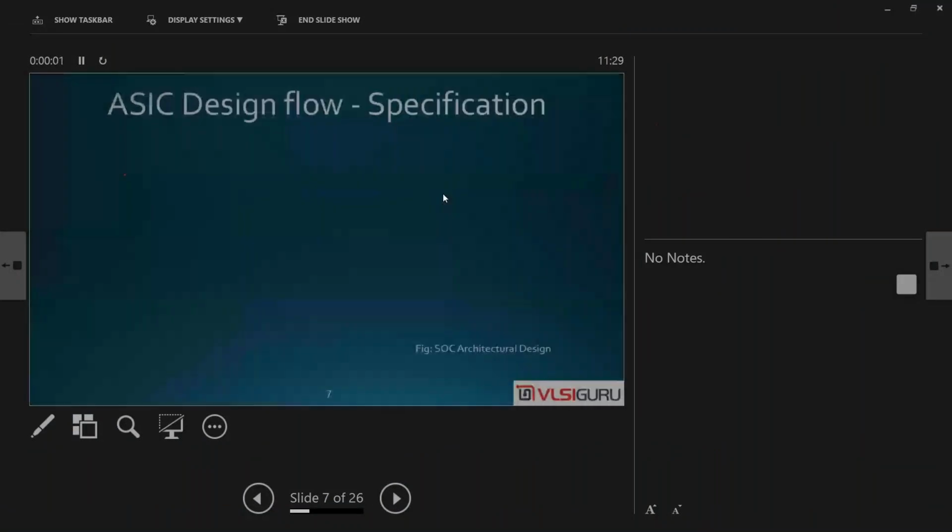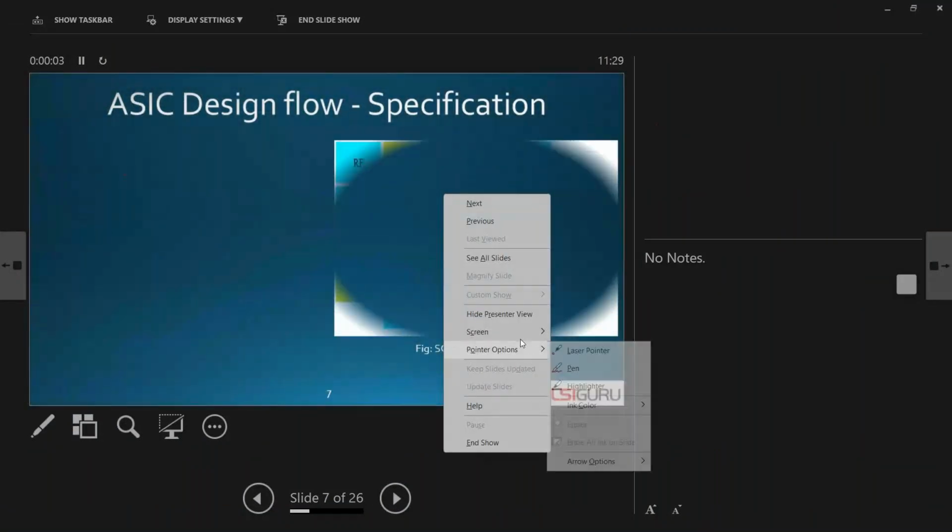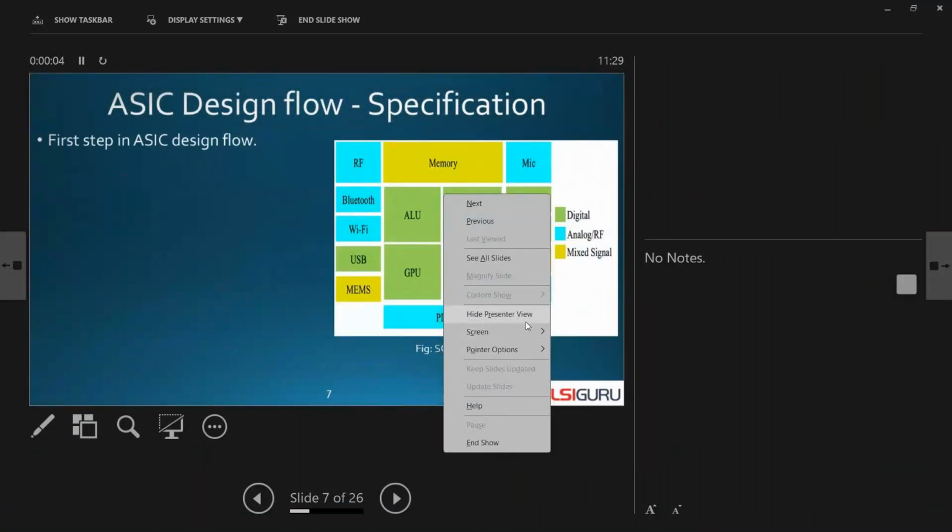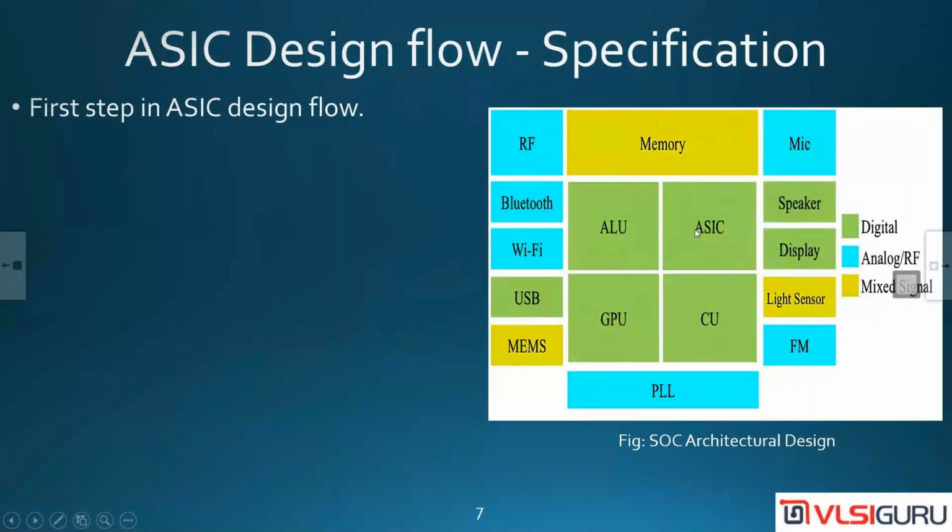So this chip has almost equivalent to how many cells? In VLSI, every term, the cell count is represented in millions. So we have 30 to 40 million cells, which is equal to 3 to 4 crores. So we cannot directly do the physical design. Doing physical design is very, very difficult because the tool will crash. So we will do physical design for only one block.